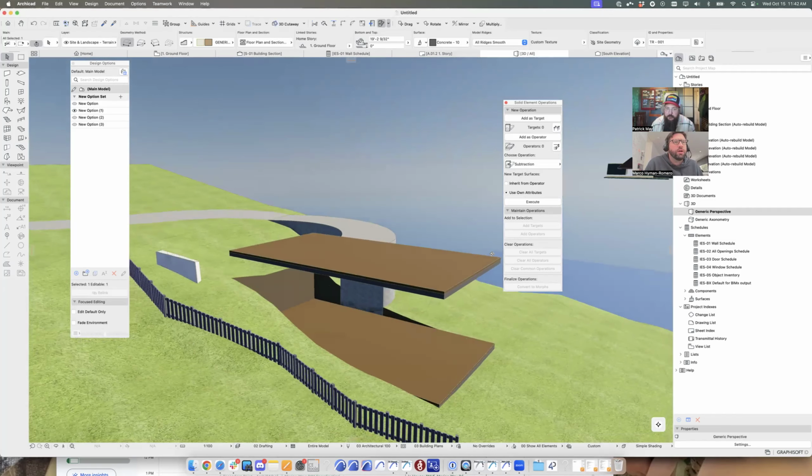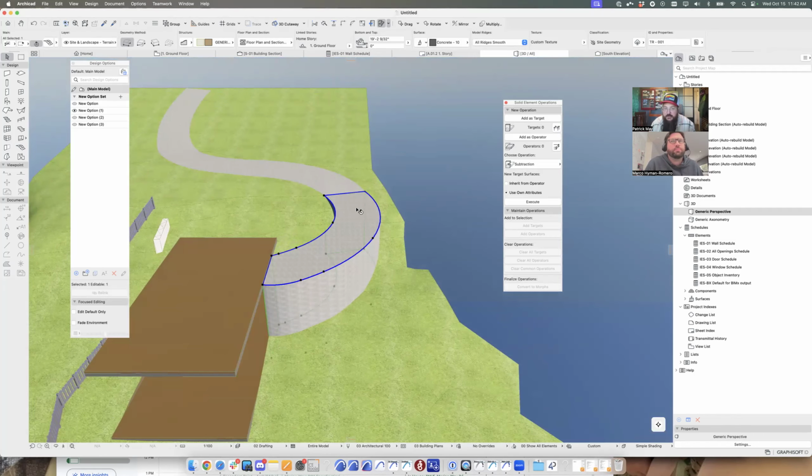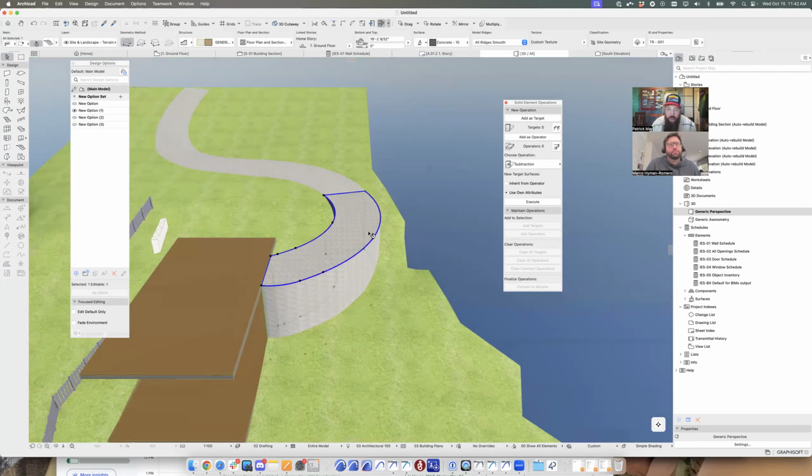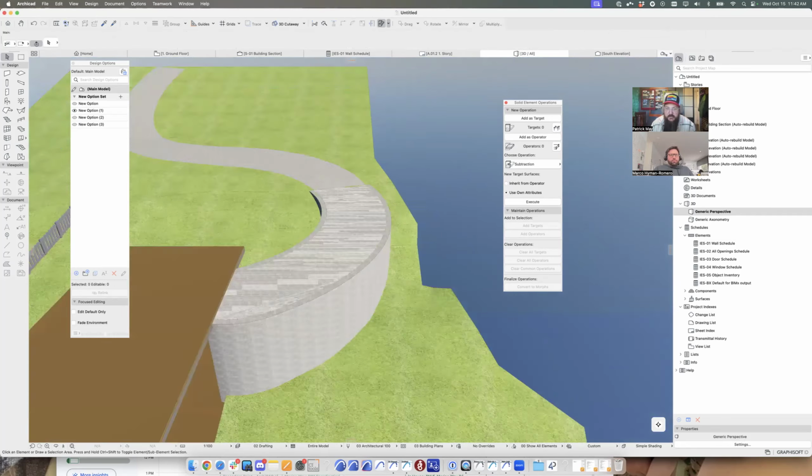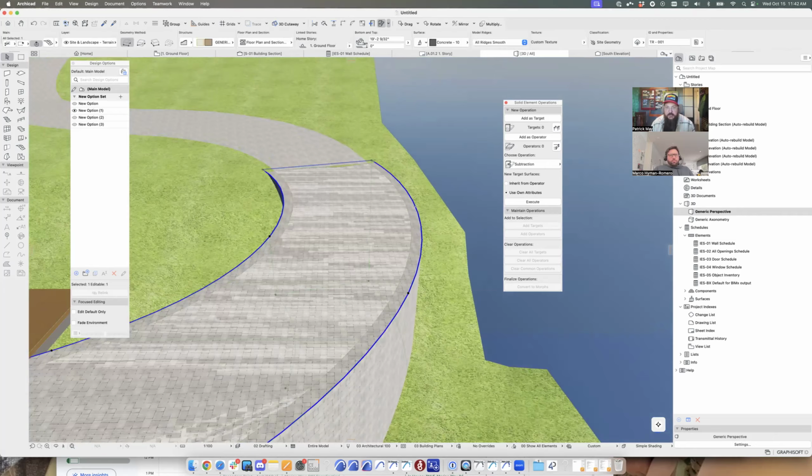Now you could do some other cool things, like if I wanted a curb or something along this edge, you can grab your offset all command right here. Offset all edges out. I've glazed over this a couple of times, but if I'm offsetting all edges and I hit the option key, it gives me a little plus symbol on my cursor. So I could say I want a 12-inch curb outside of this. That's going to add a mesh to the outside, 1 foot bigger than the inner mesh.